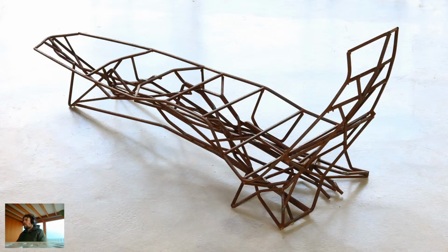So for instance, when parts of this model were self-intersecting, we would move the pieces of steel slightly so that they weren't self-intersecting. Where parts of the model needed to be very accurate, like on the top of the chair, we would carefully follow the holographic guide to ensure we were getting maximum precision. And where they didn't need to be as accurate, like in the bundling structure, we would more quickly bend the parts and pay less attention to how closely we were following the hologram in order to reduce the fabrication time.